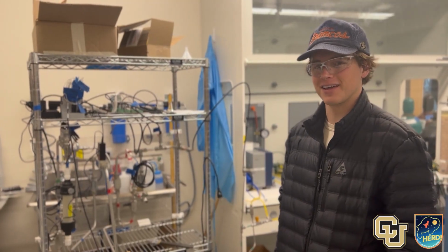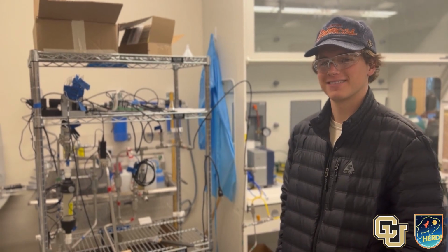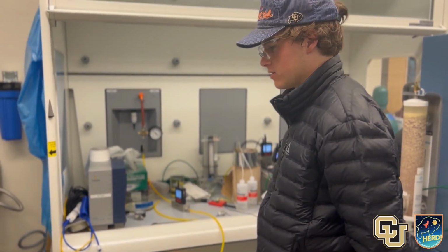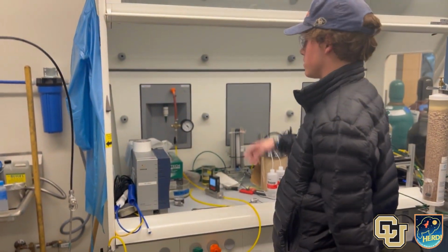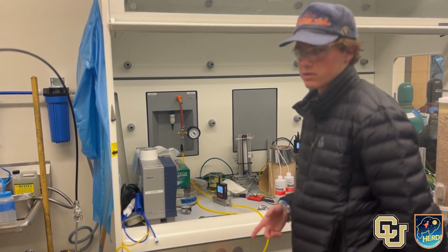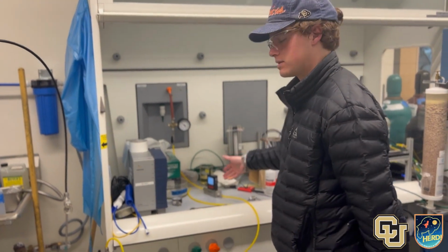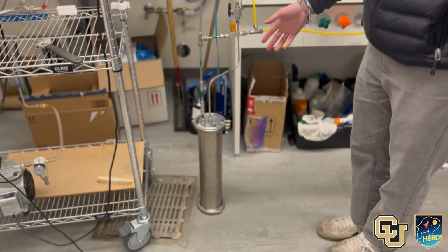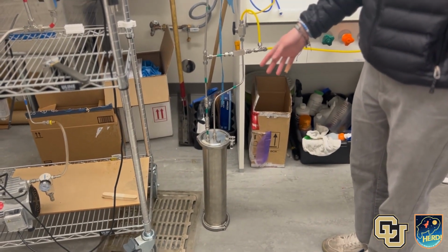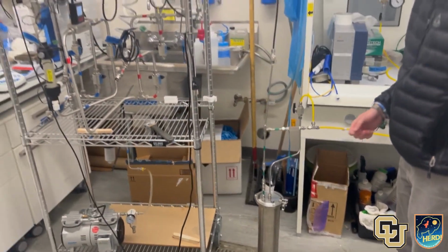Hi, my name is Cody, and I am in charge of the lab supply air. The lab supply air is in charge of supplying all the simulated metabolic outputs. It starts with the lab supply air, which is basically this atmospheric air coming into this flow meter and into our sparse humidity system, which we are able to control the amount of humidity that is input into the system.